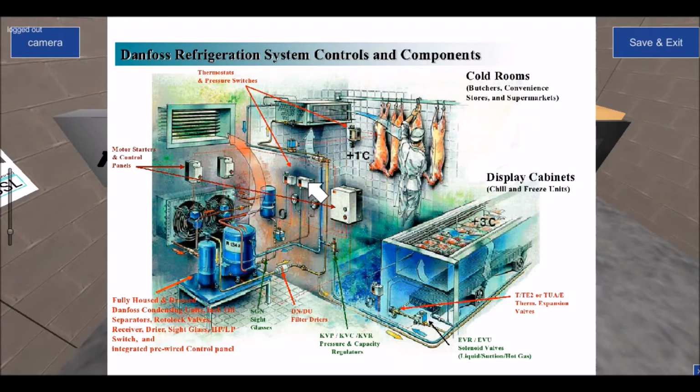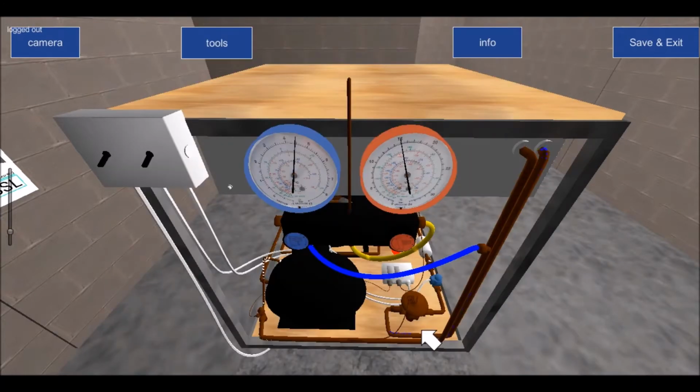So the low pressure switch then, as soon as the predetermined pressure, and normally it's about 2 bar, as soon as the 2 bar back pressure is reached, that closes the contact on the low pressure switch, which then sends electrical power to the compressor, and the compressor starts up and starts to run and continues to run until the pump down sequence starts again. So what I was trying to do is show you that.